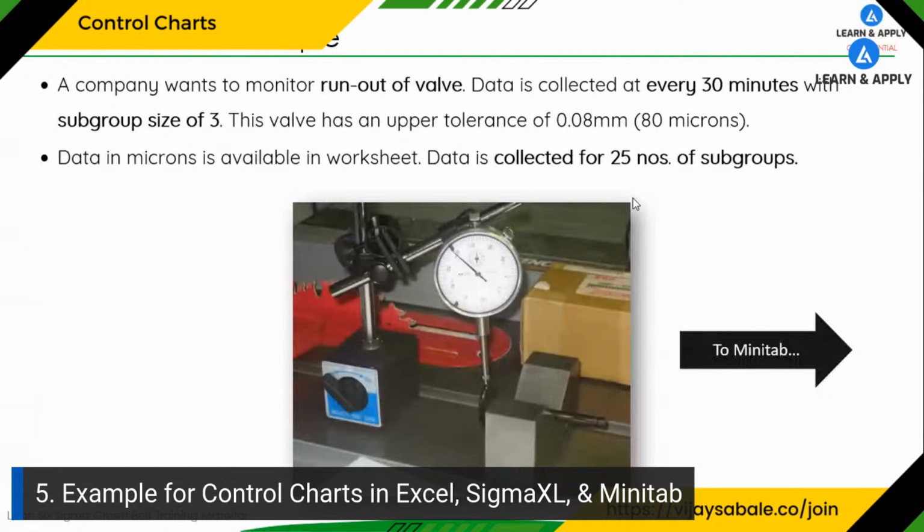The first one is data is continuous, data is collected in subgroups, and subgroup size is less than 8. So this is indicating that we need to use the X bar R control chart. This wall has an upper tolerance of 0.08 mm or 80 microns. Data in microns is available in the worksheet that I'm going to share with you. Data is collected for 25 subgroups.